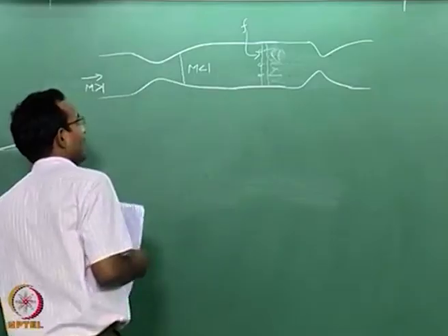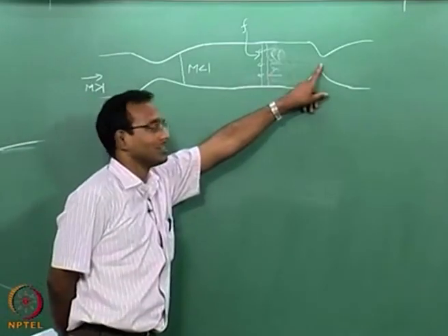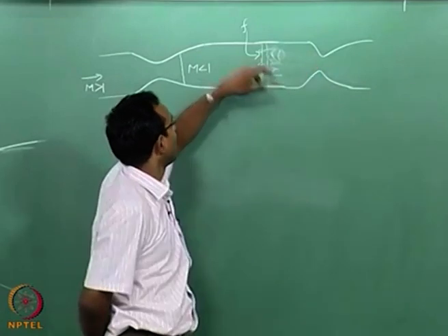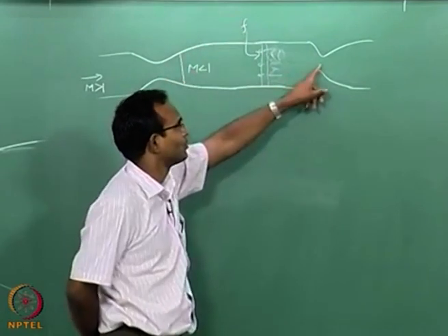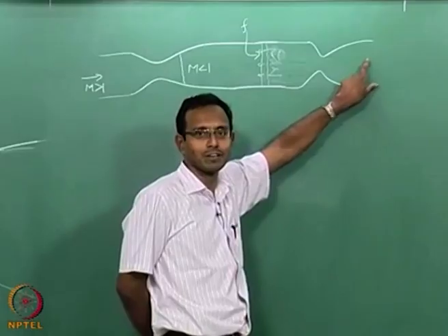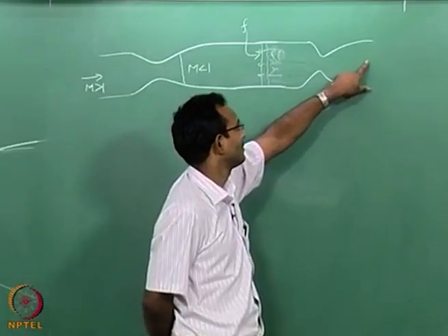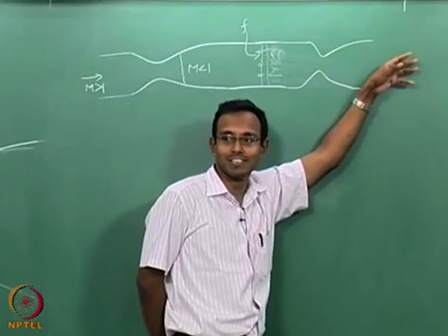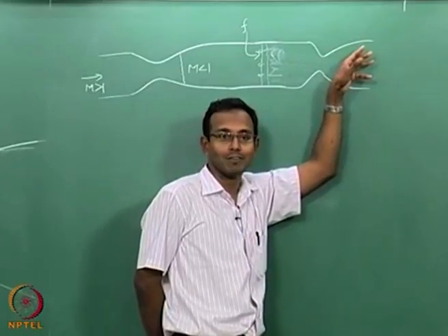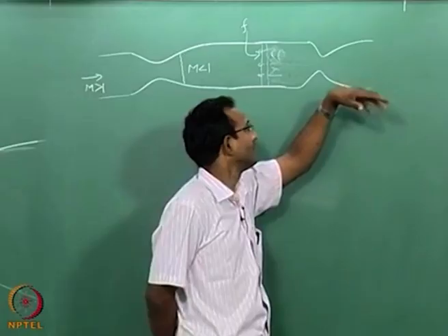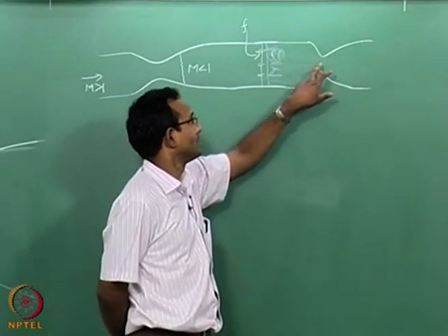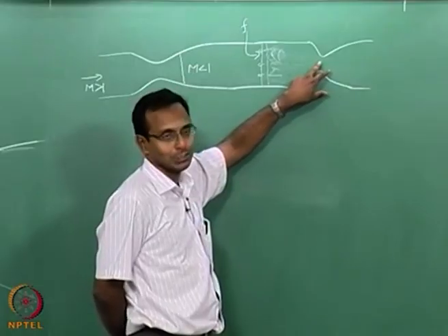Okay. Now what happens if I choke this? If I choke this point and I add a little more heat, of course it has to be choked for me to get back to supersonic Mach numbers here, otherwise I am taking the flow incoming supersonic and sending out subsonic, which is a waste and it is going to be a drag. We want it to be a thrust. So you have to think about it a little bit. It is going to be accelerated back, so here it will be typically choked.